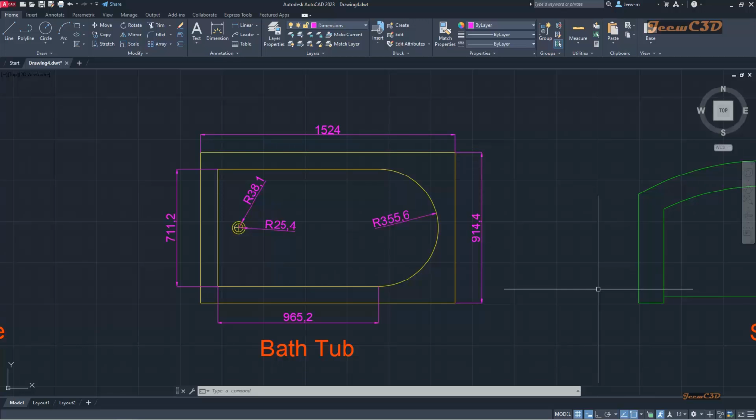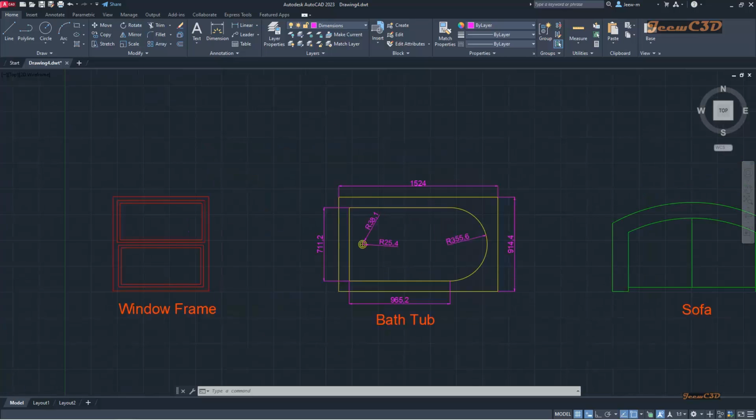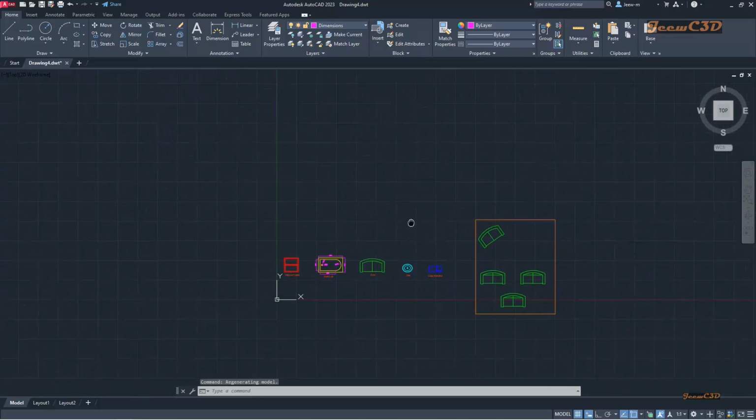Finally, we are going to talk about drawing templates. So here in my screen we have created some objects, and we have also created a block. Let us say we need these layers, and sometimes we need these blocks time and time again on various occasions in our drafting. Instead of creating this every time, there is an option in AutoCAD to save these layers and blocks in a separate drawing type called drawing templates.